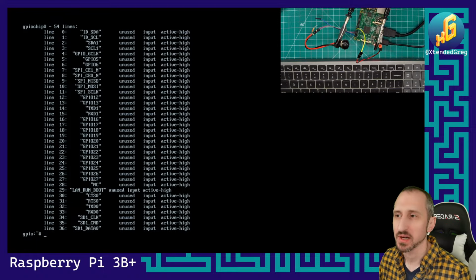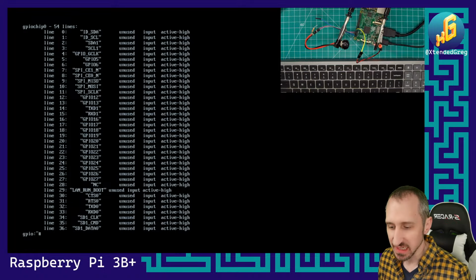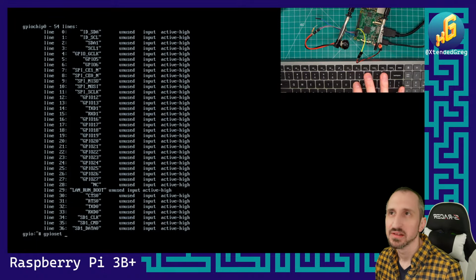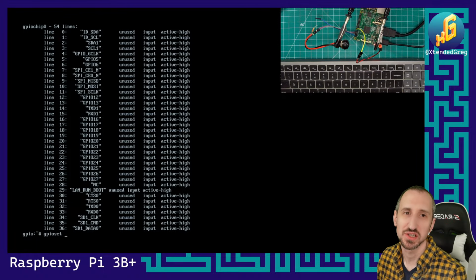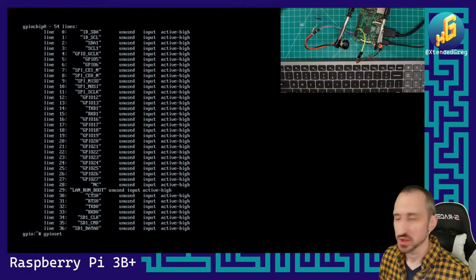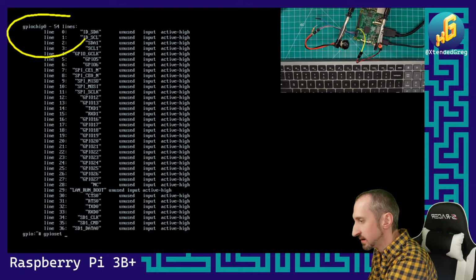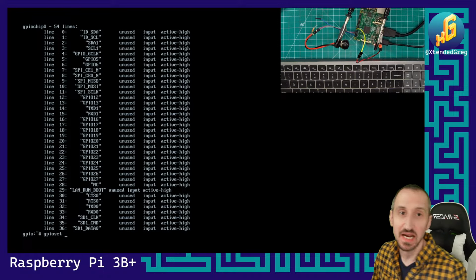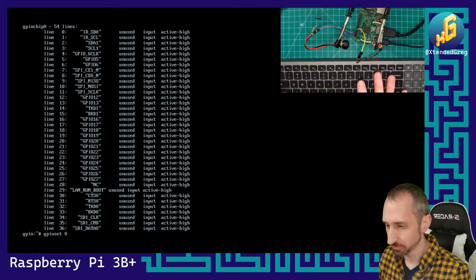So I'm just going to escape right there and go back to the command line. Let's just set our LED. Let's just turn it on. The command is gpioset. Then we need to define what board, or the chip I should say, that we're currently using, because we saw that we had multiple chips available. If we look at this, we see right here it says GPIO chip 0. We could type that out fully, or we could just put a 0 as shorthand.